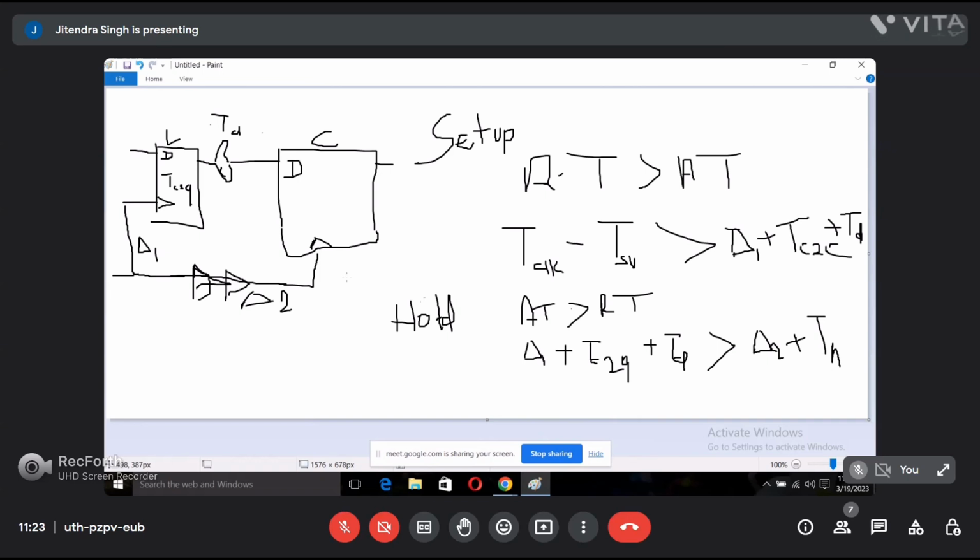Which one do you prefer, like net length? Tell me first, which pin are you checking the setup at? We have a data path with delta one buffer, clock to Q, combinational delay, D pin, Q pin, right?